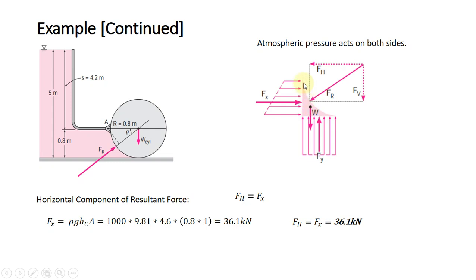So here, as you can see, we have a vertical projection, and we have the pressure distribution increasing downwards. You already know this, and we have the resultant force Fx along the x direction, and you can see that it's a bit lower than the midpoint, and that is because the pressure increases as we go down. And the other projection we have is this horizontal projection. So we have a resultant force Fy, and you can see that the pressure is constant because it does not vary along the horizontal.